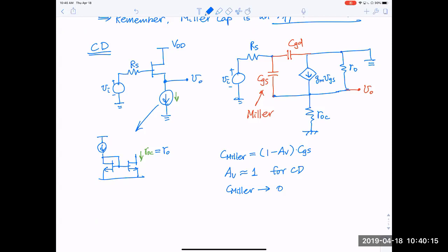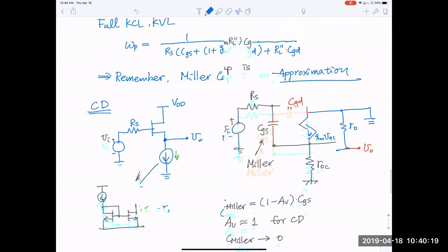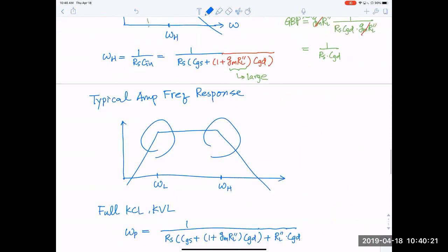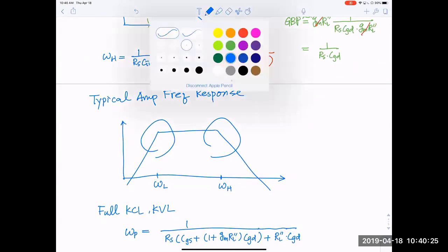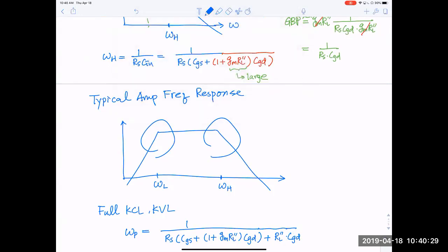And it's not surprising. I can give you a physical intuition of the Miller effect. The Miller effect is like a seesaw. A voltage amplifier is like something fixed at the fulcrum, but the output lever is much longer than the input lever.